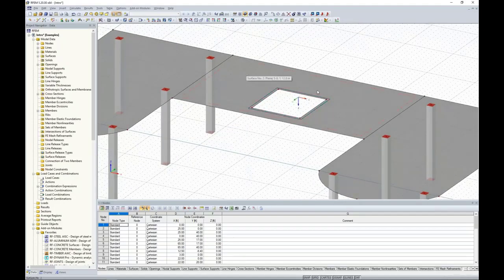So this is a pretty long span for our center slab here. What I'd like to do next is to draw what's called rib elements. These rib elements will be dropped below this slab, spanning from my columns on my left to my columns on my right. Now, rib elements are drawn slightly different. We need to first define the line and then assign a rib cross-section to it.